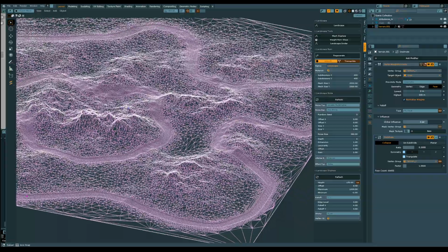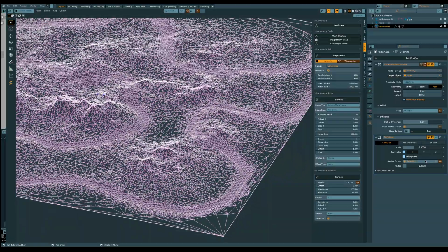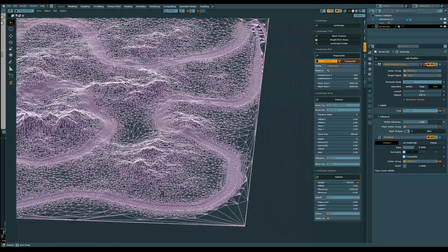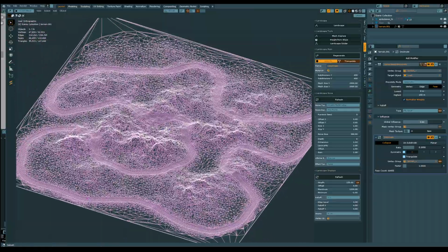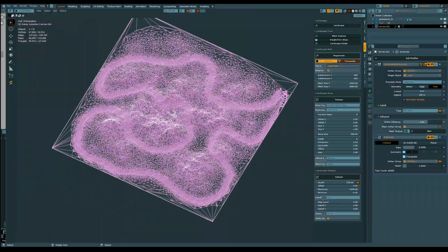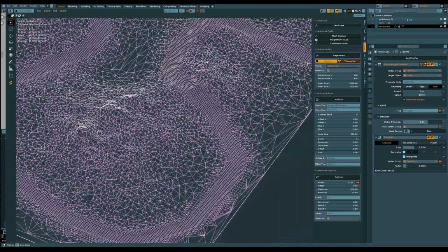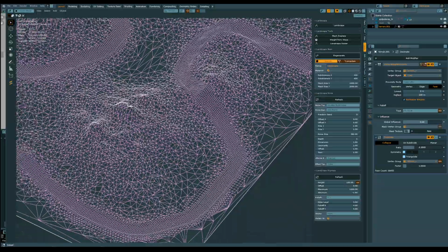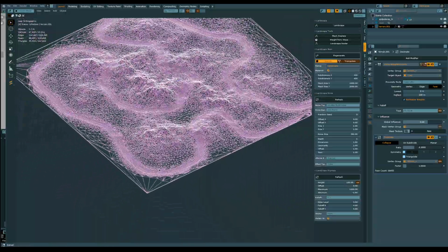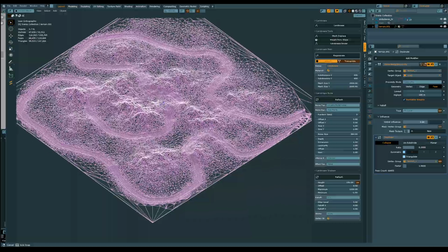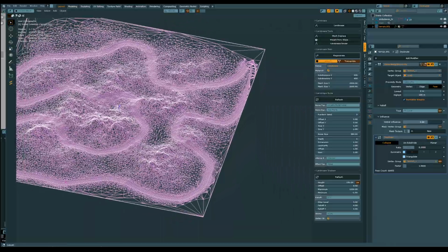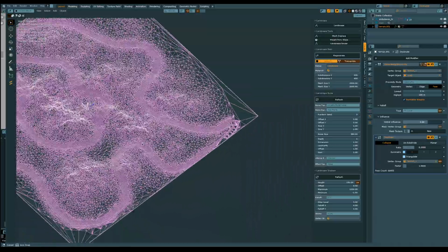All right. I forgot to specify the vertex group needs to be the terrain. So as you can see, whatever's not so close to the road is getting decimated more. Whatever's closer, the geometry is quite a bit denser. And we can continue to play with these values until we get somewhere reasonable.